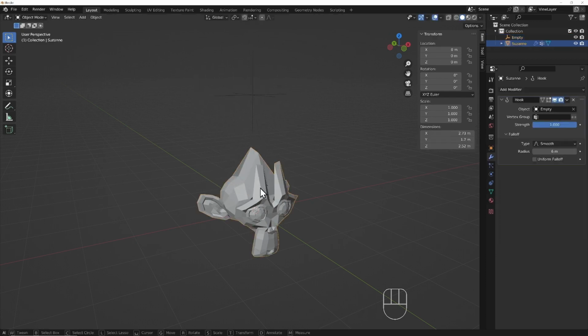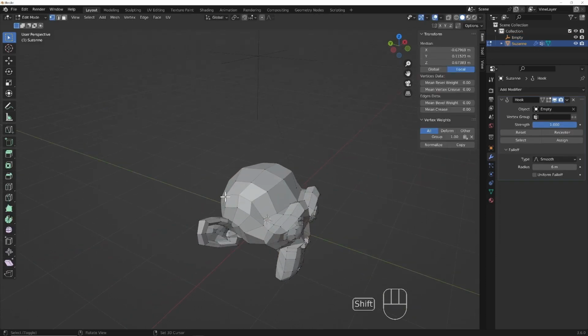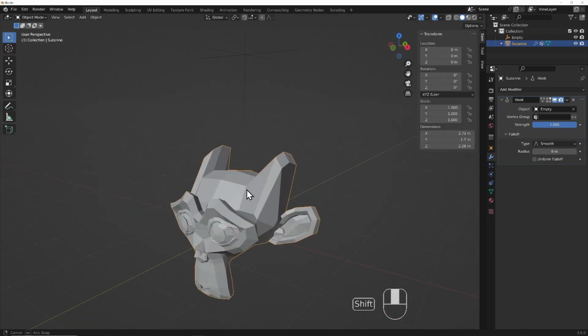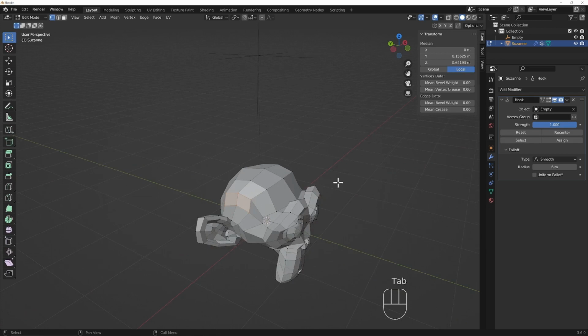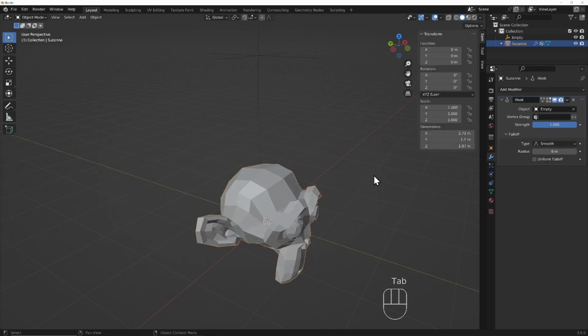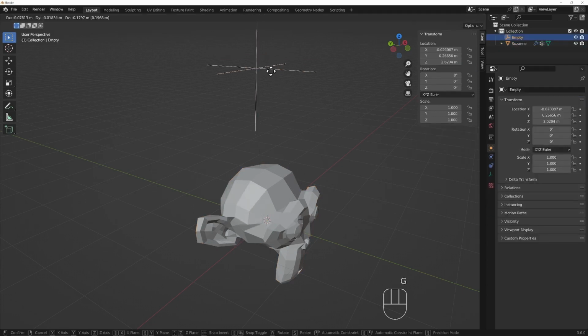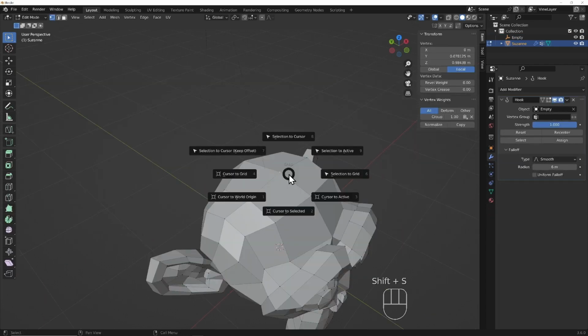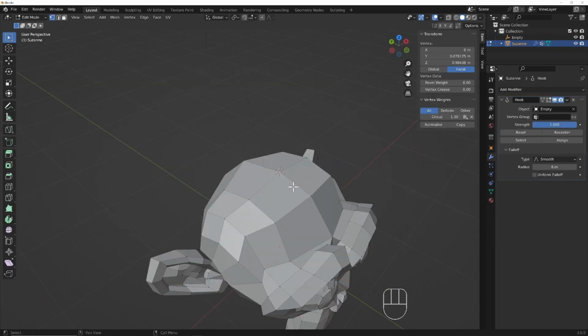However, we can reselect vertices at any time and adjust the selection without having to unassign anything. Resetting will cancel the transform, but it won't reset the position of the empty controlling the hook. Recenter will place the hook to wherever the cursor happens to be.